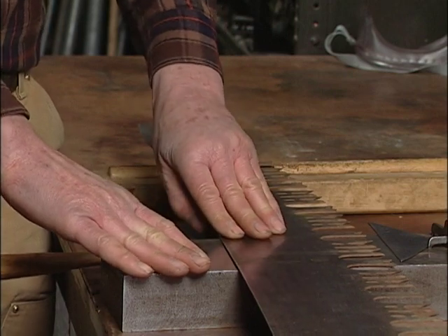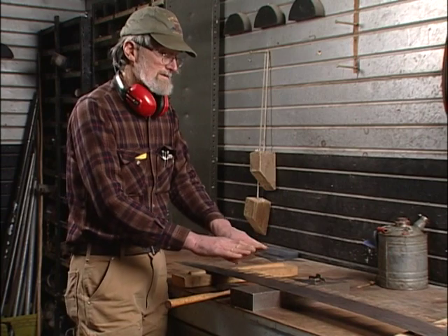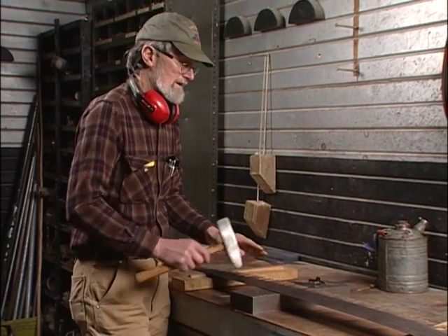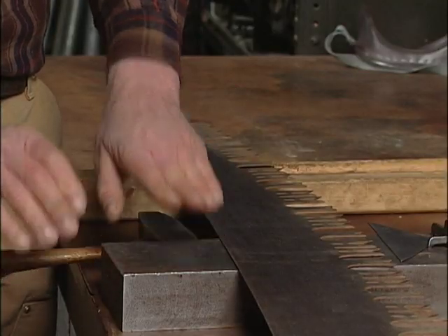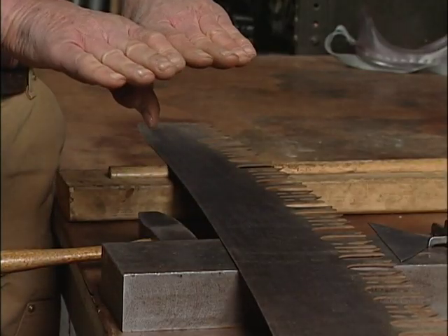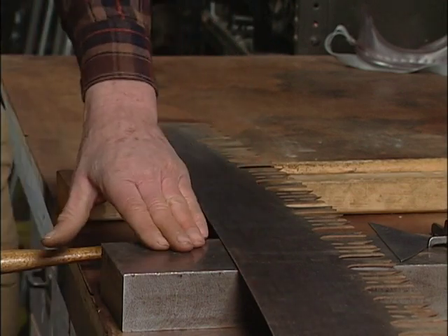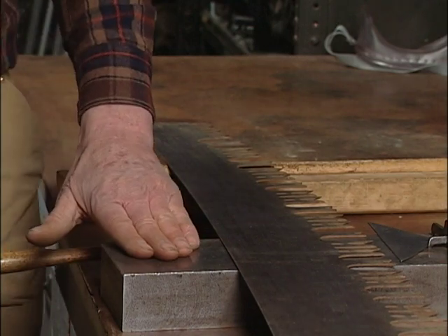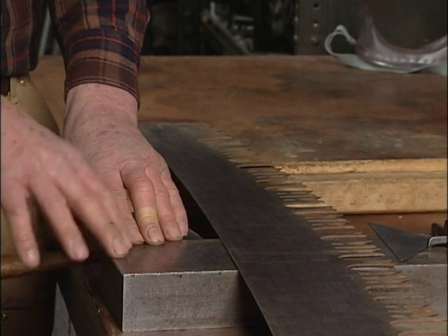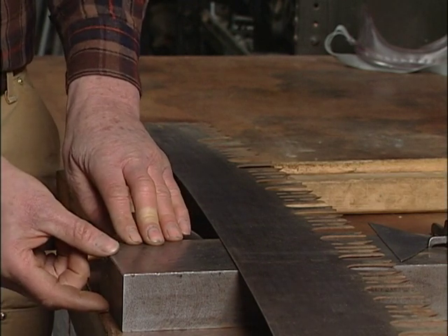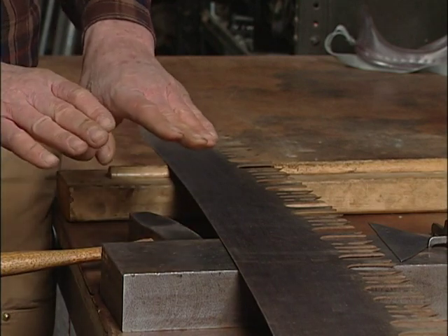What is helpful is to have an anvil which is relatively soft. It has some give in it, so that when you hit the saw with a hammer like this, the anvil behind it gives a little bit and allows the metal to bend. And so what I find works really well is an anvil which is made out of mild steel. This particular anvil is made out of a piece of 2-inch plate, weighs about 40 pounds. And so I found it works very well for taking the bend out of a saw.